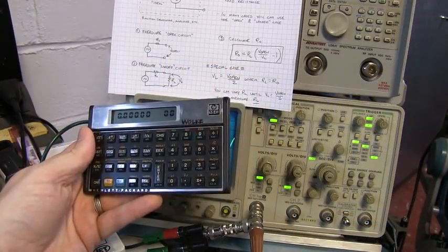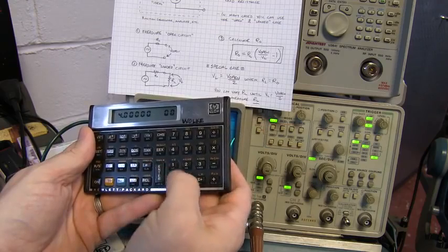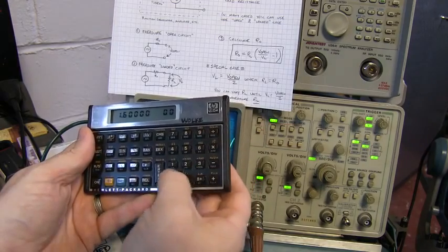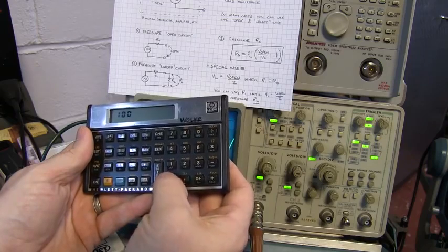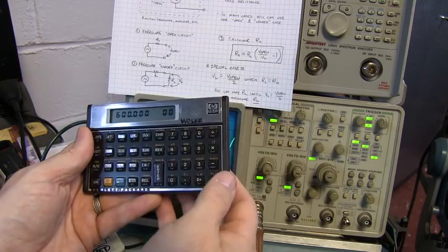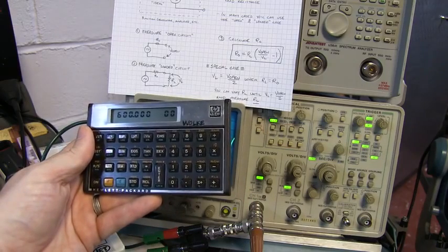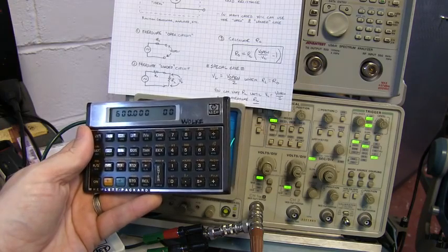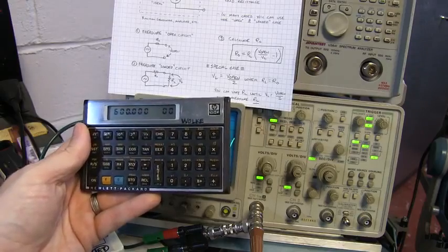Okay, so let's calculate our output impedance. Our open circuit voltage was 4 volts. We divide that by our loaded voltage of 2.5 volts, subtract 1 from that, and multiply by our 1000 ohm load resistance, and we wind up with 600 ohms. And that makes sense. When I designed this thing 25 or 30 years ago, I was probably looking at audio circuits that typically work with a 600 ohm impedance. So that all worked out well.